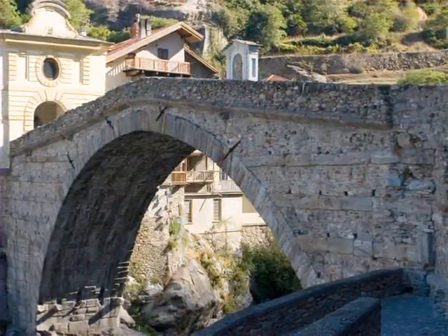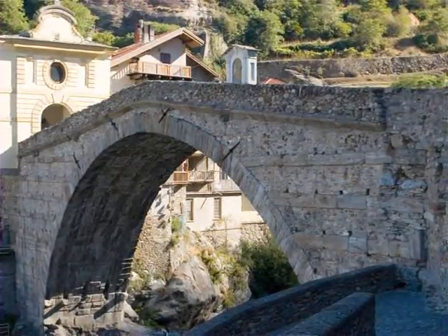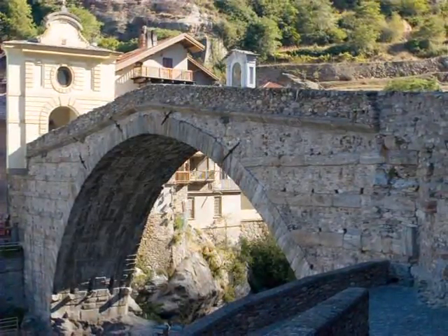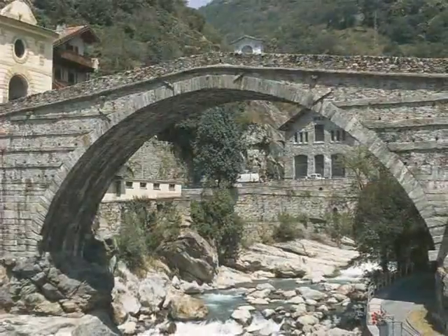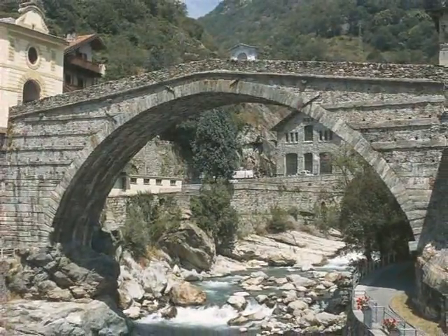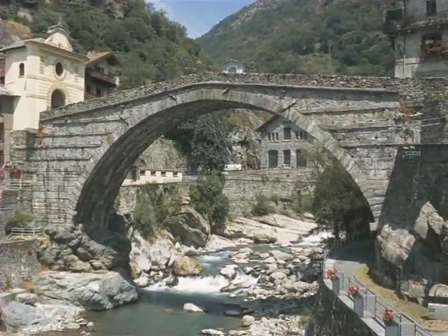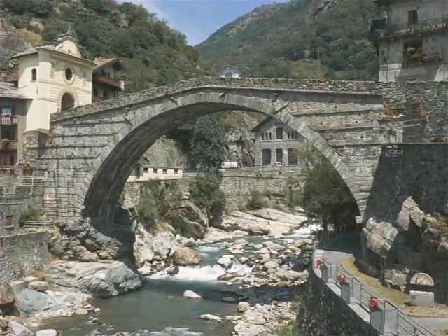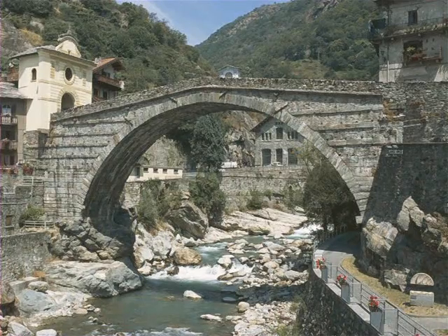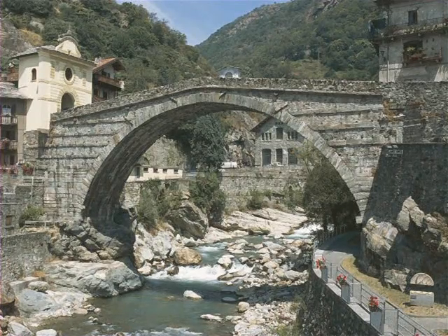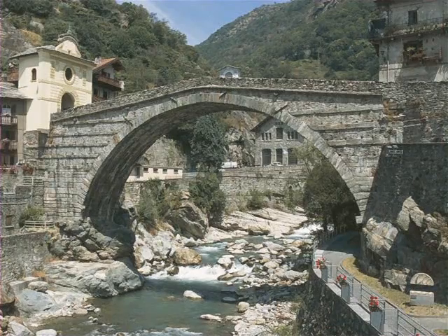With that little demonstration as review, now let's begin our study of Roman arched structures with one that we've already encountered in a previous lecture, the Pont Saint-Martin, a beautiful stone bridge constructed in northern Italy in the 1st century BC. Now this is just about the simplest form of arch structure one can possibly imagine. A single semicircular arch supporting a single-lane roadway. Yet this 103-foot span is actually among the largest of any Roman arch that survived from antiquity.